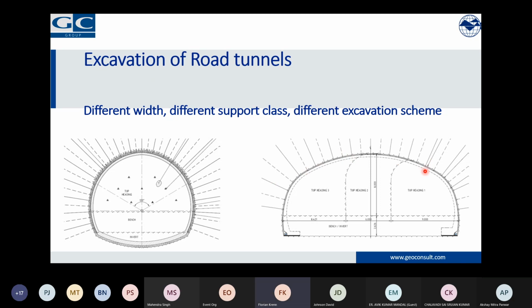Now this, just by looking at it, and the bolting pattern looks like it is better rock mass, but due to the size, there was a subdivision in different pieces of the top heading. So, and this is now a technology which is more or less associated usually with caverns, like also in some rock caverns, where usually a pilot is made and then the side slashings are coming, depending on how the contractor is comfortable. Usually such a large cross-section can only be done in good rock with that support as it's shown. So logistics become an influencing factor how you subdivide your cross-section.